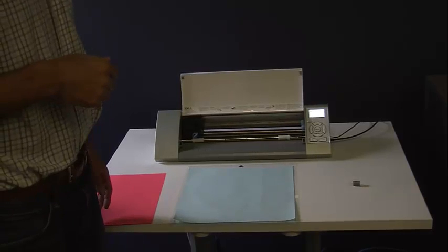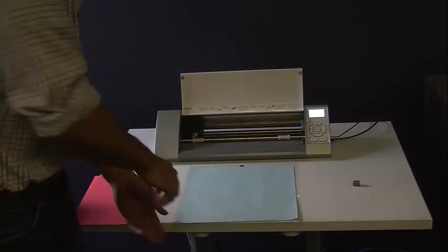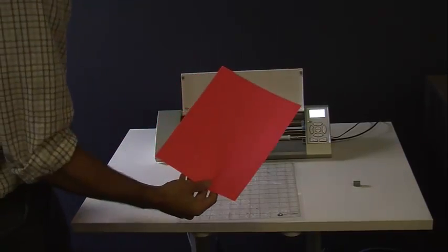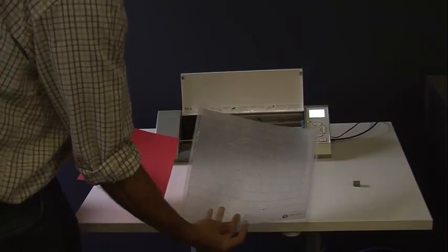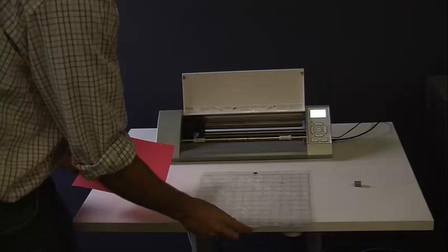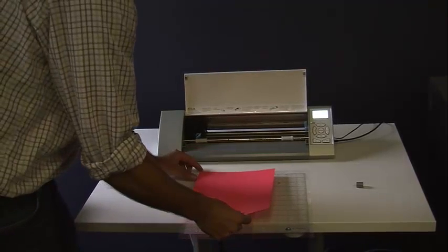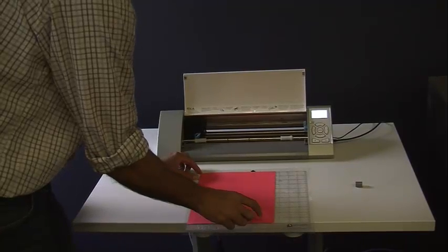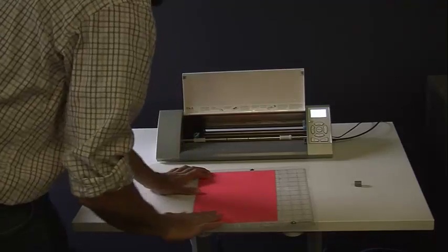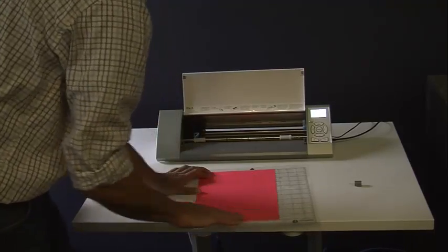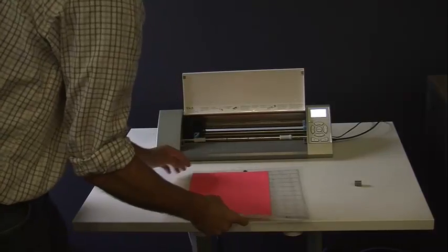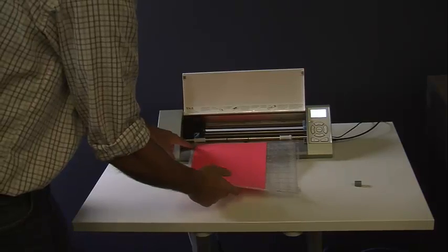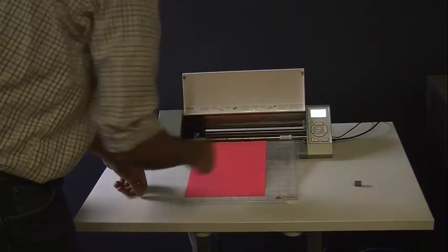To load the materials into the Silhouette Cameo, we'll need to use the cutting mat. Peel off the protective layer, take your material, and make sure the arrow is pointing up on the cutting mat. Align so that you have a straight 90-degree angle along the edges. Press down firmly so that your material sticks to the cutting mat. Align with the edge indicated by the arrow on the Cameo machine and press Enter to load cutting mat.